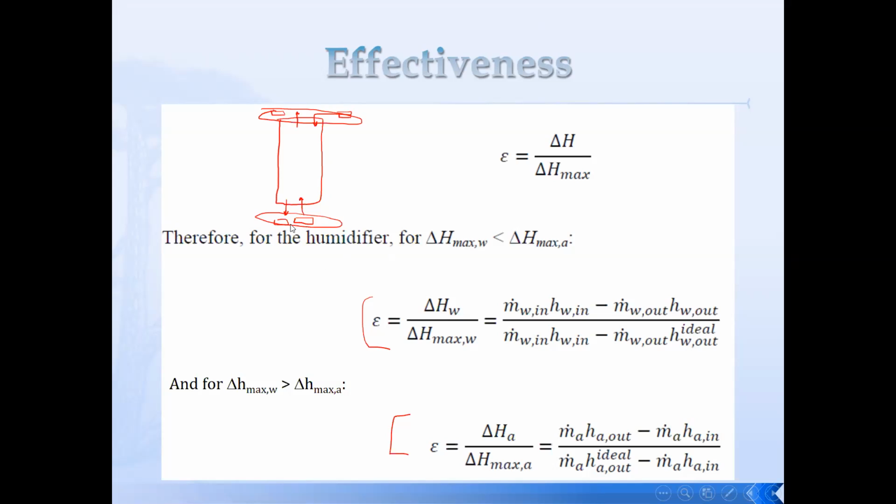But I have to tell you that it's not just a straightforward value that you can calculate, but you need to go through the unit piece by piece to identify where this point is. Sometimes you do it graphically, and sometimes you have to use an iterative technique, or at least go line by line or piece by piece, as I mentioned, to reach the lowest difference of enthalpy.